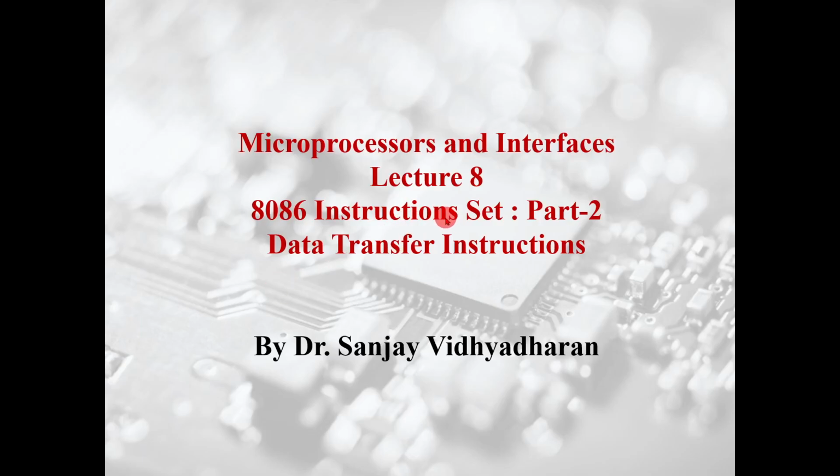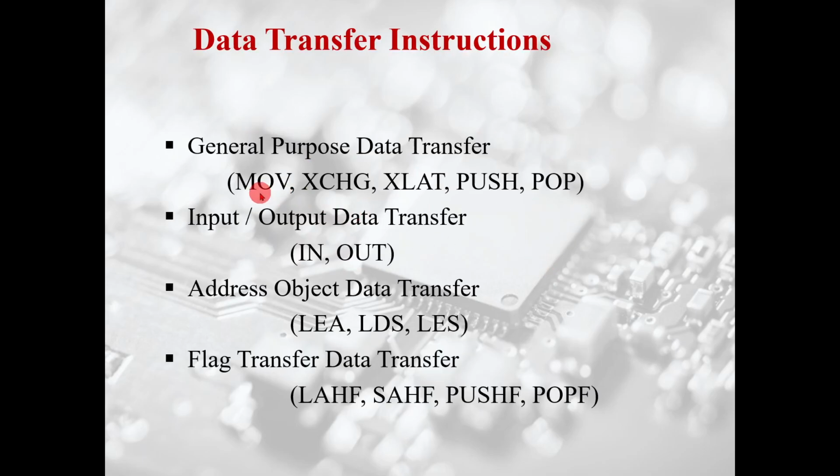In the last class, we started with the 8086 instruction set. I will continue with that and we'll continue with data transfer instructions. We already had a look at the move instruction, exchange instruction, XLAT, push and pop. Today we'll see in-out instructions, LEA, LDS and LES instructions, and also the flag transfer instructions.